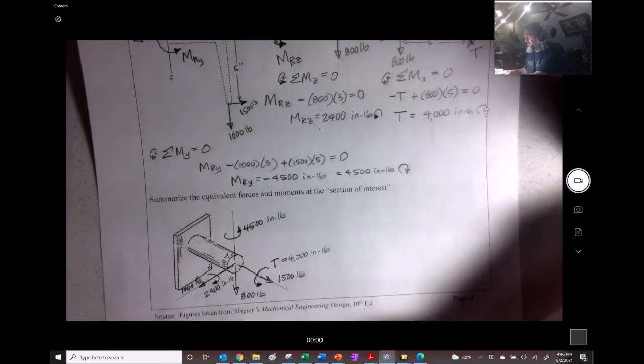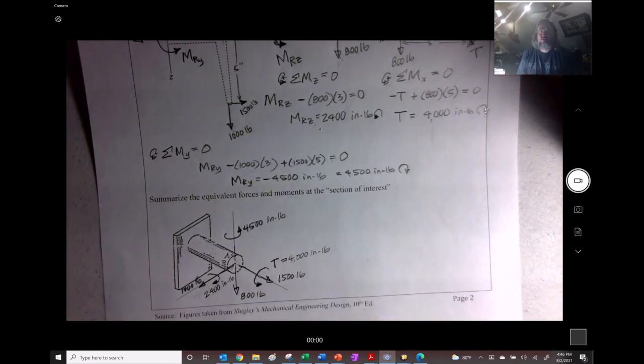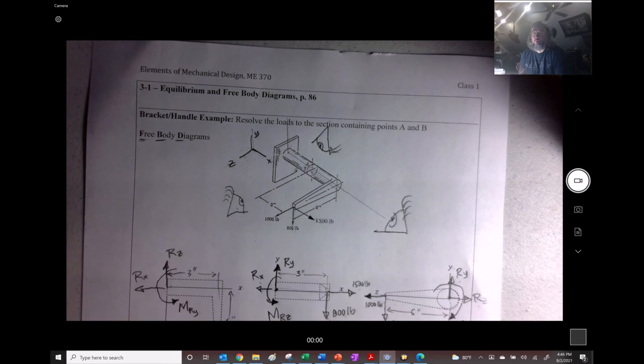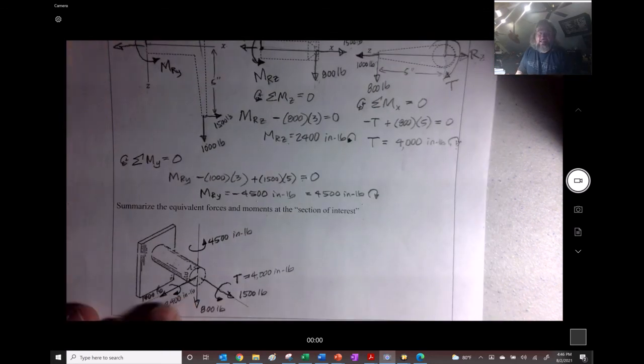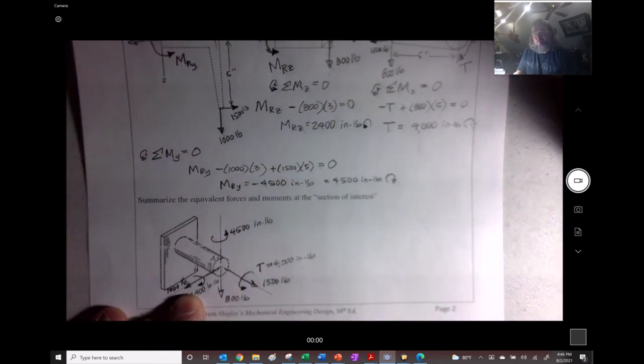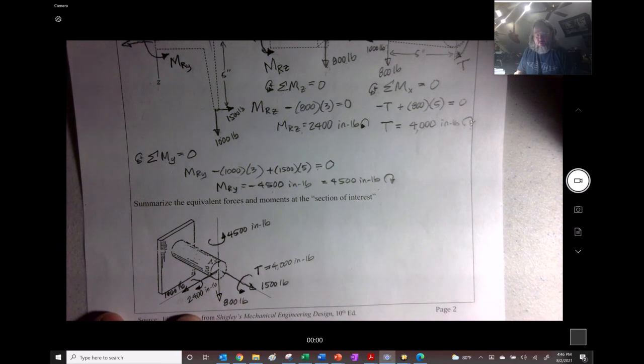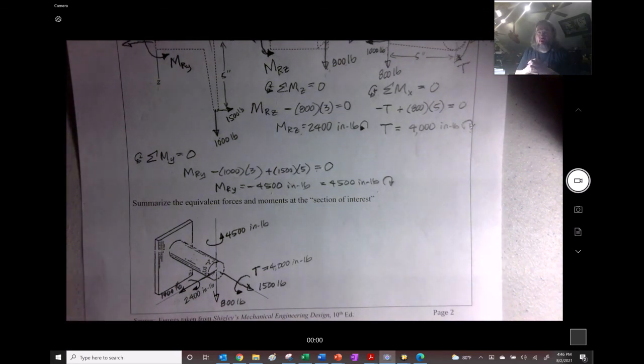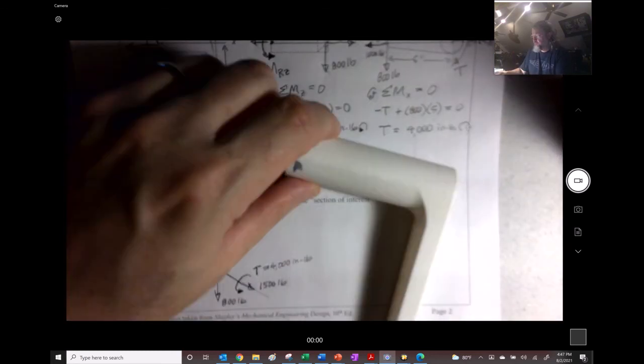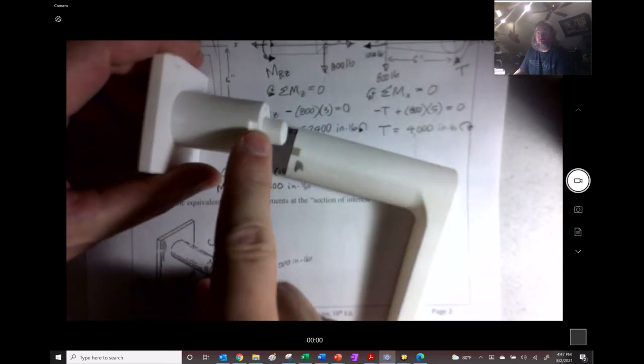So I think I have a demonstration where I do a cross product. And you'll see when we do a cross product on a problem that looks like this right here, we're actually going to get this answer. These are the directions that we will get for our answer when we do a cross product. And they are what we'll call the equivalent moments, right? Equivalent moments because we moved the location of the forces from here to over here.